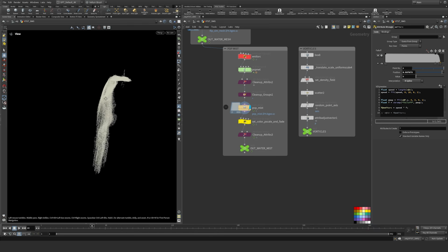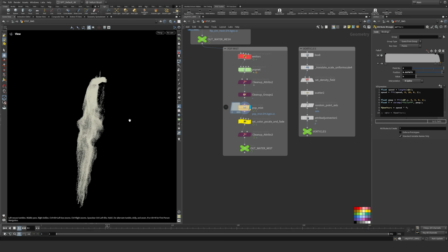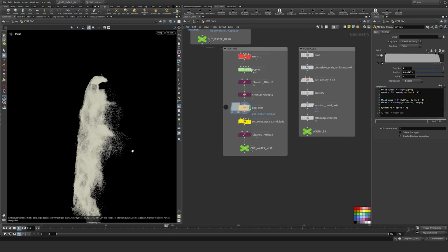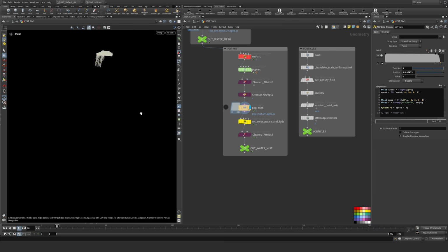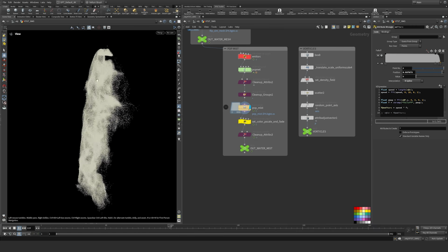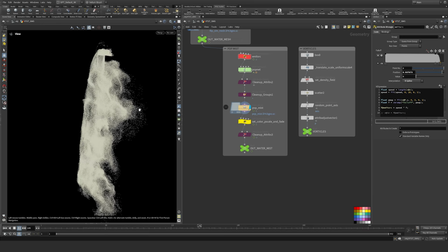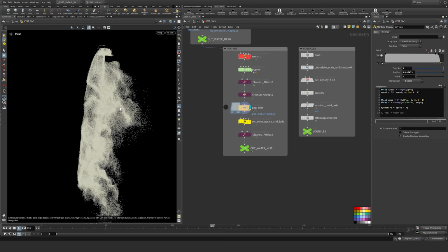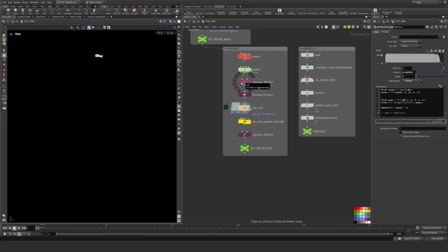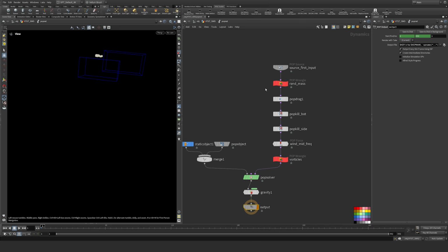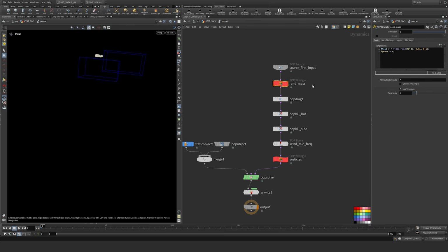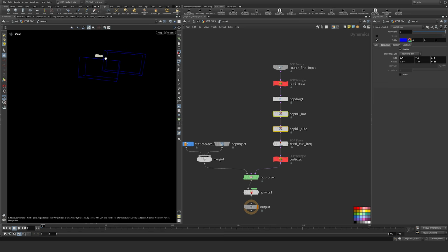And this is basically just using some pop forces to waft off some of the particles that are across here. So we get the emission coming off of that mapping, and then we have some lighter particles that kind of drift in the air, essentially. Just to show some of the setup in that, there's some randomized mass, some pop drag, some kill geometry just to get rid of some overspill that was happening.